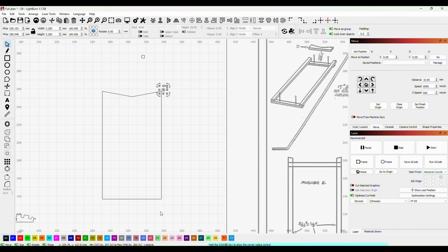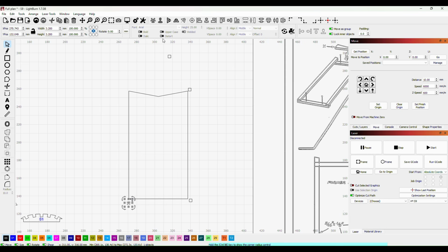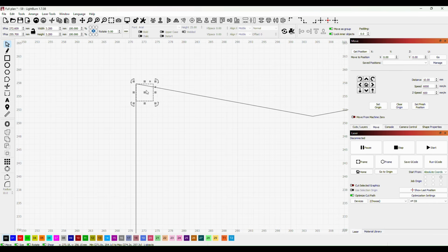can put one there, put one there, put one there, and I'll bring that one down to here. And all I'm going to do with those is make sure that my top left corner is level with the top left corner here. Now what this means is, because the dihedral is going to come up, when we fit this shape in, we're going to have to ease the end of the longeron.